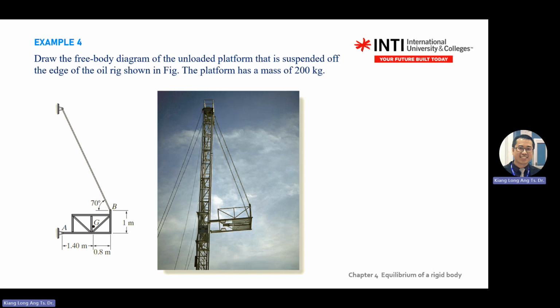Okay, so you have a pin here. You have a pin. You have a cable. You have a mass. So how many forces do you have? 1, 2, 3, 4. You have 4 forces. Right? No moment. Okay, no moment on the diagram.